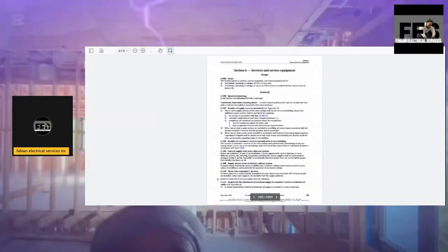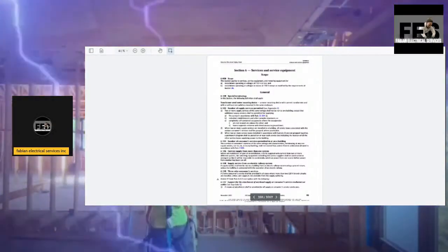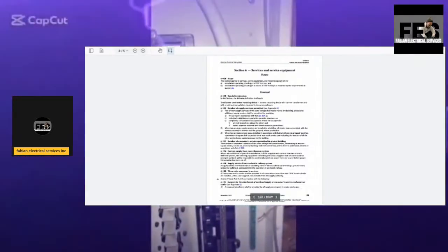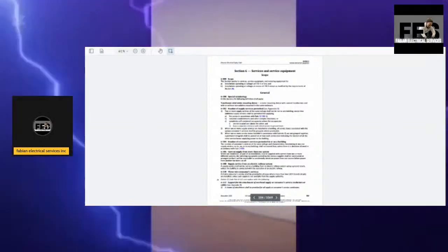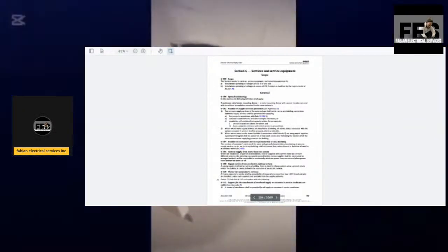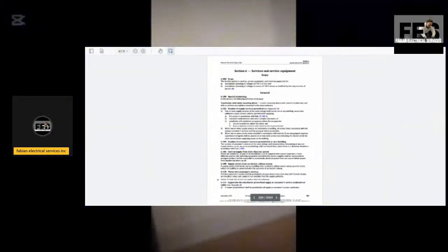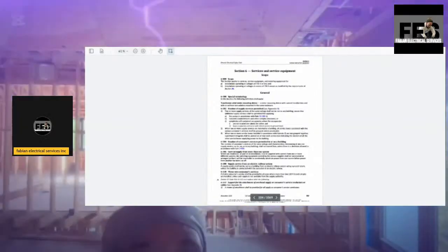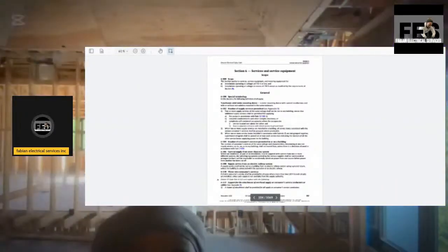Industrial establishments and other complex structures or complex self-contained occupancy where the occupancies are not located one above the other and have a separate entrance with direct access to ground level. It also goes on to say when two or more supply services are installed to a building, all service boxes associated with the various consumer services shall be grouped where practicable.